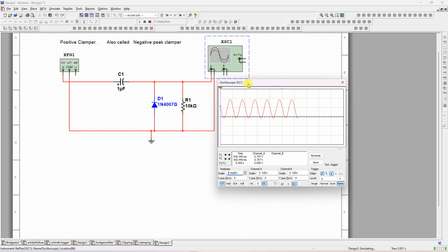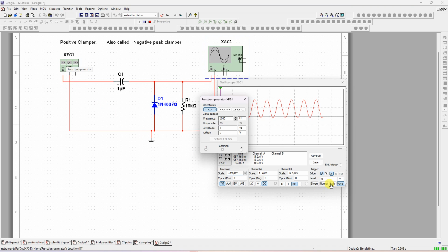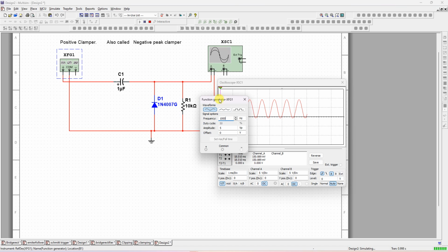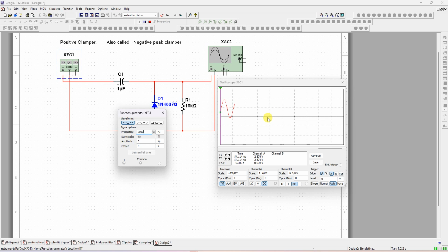Now if I try to increase the amplitude, the waveform grows positively. So let me check whether it is possible or not. I will try to check whether, if I increase the amplitude, the waveform's negative peak is clamped here only. Waveform will grow upwards.